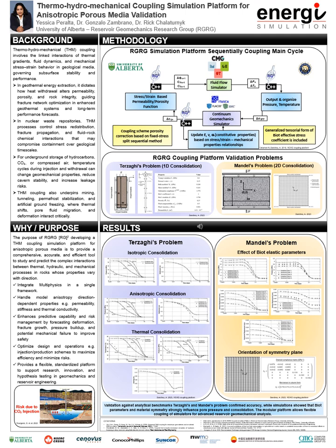Thermo-hydro-mechanical coupling, or THM, describes how heat, fluids, and mechanical stresses interact underground. These interactions are key to understand the stability and performance of subsurface systems. For example, in geothermal energy, THM explains how heat extraction changes rock properties like permeability and porosity, helping optimize fracture networks and predict long-term performance.